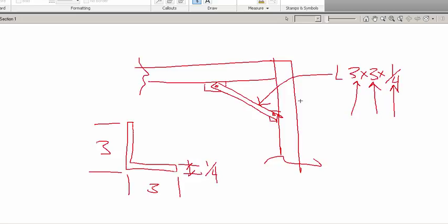Makes sense. So they can be 3x3s, they can be 4x2s, they can be 5x4s. There's a lot of different variations of the legs. They don't necessarily have to be equal. But I do want to draw attention to the fact that I drew an L right here. Technically, it's really supposed to look a little bit more like this, implying angle. Most of the time on a set of plans, you're going to see people use the L versus the actual angle alligator's mouth symbol. Either one means an angle. It's just that most of the designers aren't getting too picky about having that extra slant to it. So what they do is just use a simple L to type it out. Okay? So make no mistake, technically this is the more correct, but you're probably going to see just an L is the thing that they use most of the time. Alright?